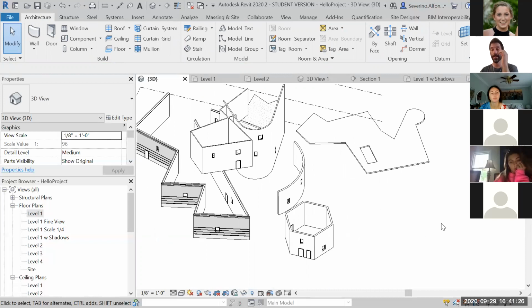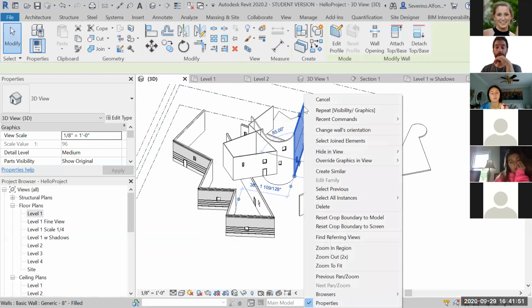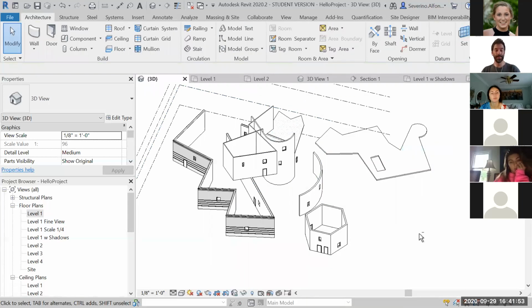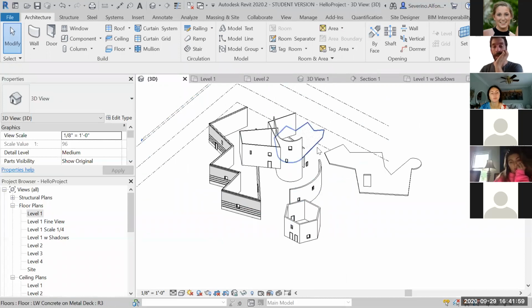The light bulb, on the other hand, is a less temporary, a bit more fixed solution. And I normally explain it this way: you enter a room that is completely dark, and you want to see everything, so you turn on the light bulb. So whatever is hidden or dark will be shown. Let's say, for example, I right-click, hide element. And I keep working and I don't remember that I hid that wall, because I did not do it temporarily. I actually did it quite permanently, which is the right-click option.